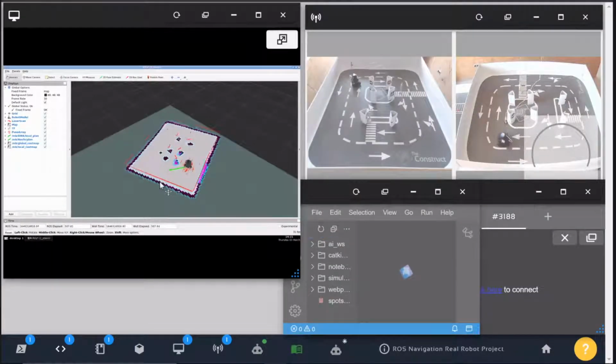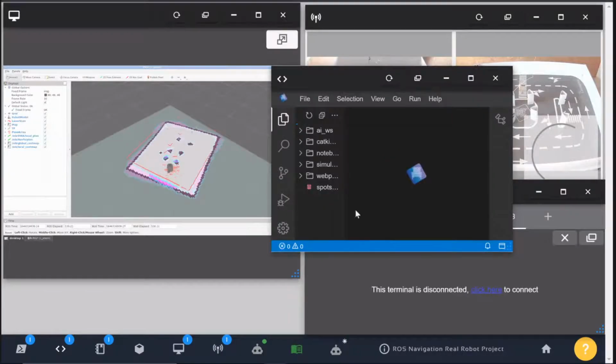Yes, oh, there we go. Nice. And it looks like the tuning of your AMCL, I'm sorry, your move_base parameters are quite right, because especially in small environments like this, it makes it so hard for the move_base to find the goal. So good job there. It took a lot of time.